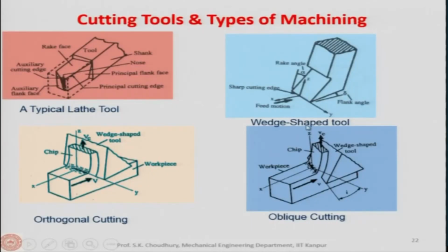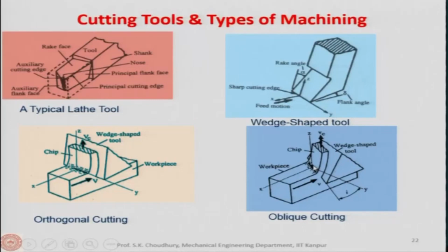cutting is three dimensional, because the cutting forces will be now located in all planes like x, y, z plane, okay, and the chip will no more be flowing exactly perpendicular to the cutting edge, but it will be inclined with respect to the z axis and inclined to that side where the resistance to flow will be less, that we will discuss later.